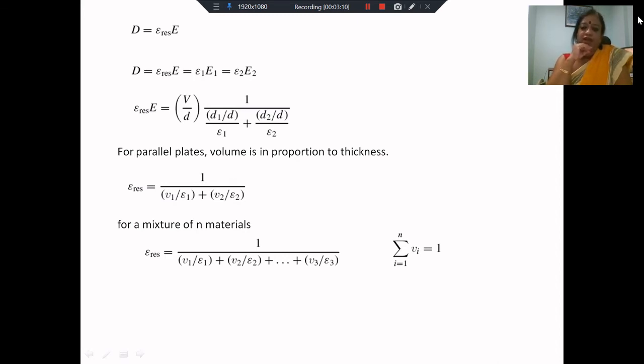As you remember, the reason that we use multi-layer dielectric systems is because when you use a single layer of dielectric, there might be random distribution of weak regions. In these weak regions, you may have an encapsulation of a lower permittivity material. And as we know, whenever we have a lower permittivity material adjacent to a higher permittivity material, the lower permittivity material is in special danger of discharging or breaking down. So when you use several layers, even if you have a distribution of weak points, these weak points are unlikely to form a bridge or a continuous weak region between the two electrodes. Instead, these weak regions will be randomly distributed along the area, and adjacent to a weak region you will have a strong region, and on average the dielectric is likely to perform better. But this is something that we have already discussed.